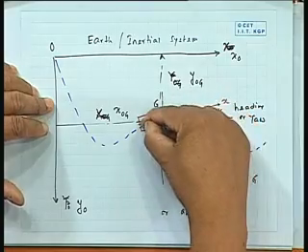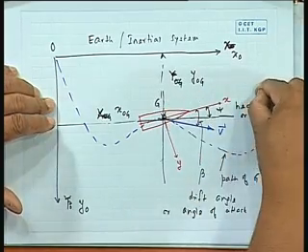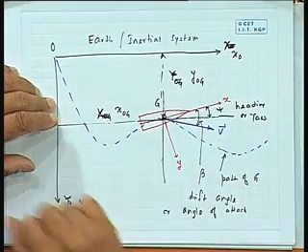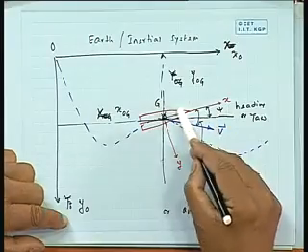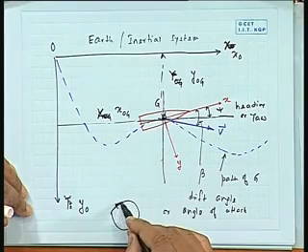So, you see when the ship turns, this is a very common thing. No ship can ever turn when the path line is exactly the same as the heading line. You have to have an angle of attack beta. When the ship turns, you all know, it cannot turn like a car exactly following like this, it just cannot turn, because no forces can be produced if you turn that way on the y direction. So, you cannot turn like that. What I mean is that you cannot have a turning when the ship is exactly parallel to that.